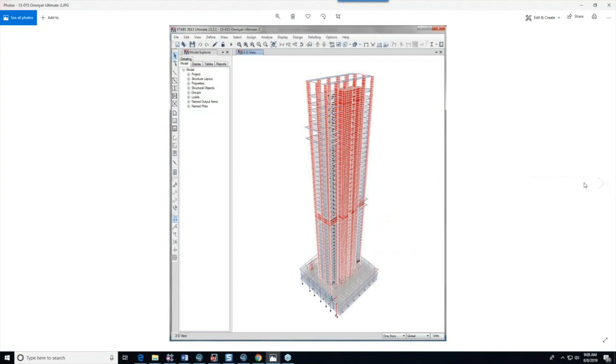And then what about transfer slabs? You know, if we have a rigid body diaphragm and we're bringing forces down from a tall building, let's say, and at the base of the building, we're going to transfer some of the loads from discontinuous shear walls. And of course, it's something that makes all structural engineers cringe if they have these kinds of discontinuous shear walls.